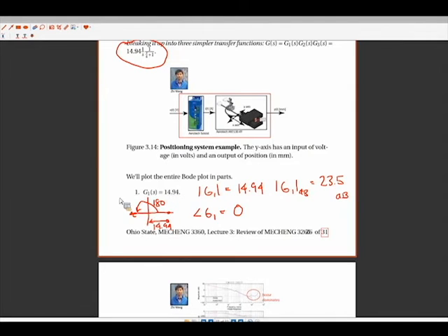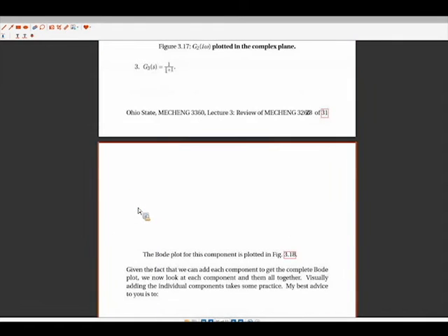Okay. So that was a little aside. That's not actually part of the notes. Going back to the op-amp example, the purpose was to multiply by -2. That's why the low frequency phase was 180 degrees. There's a gain of -2. So we have this first component, magnitude 23.5 decibels, phase of 0. Going down to the region of the notes that has this Bode plot.